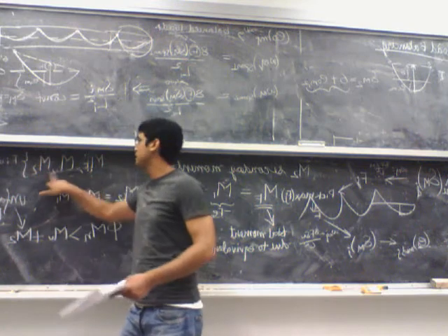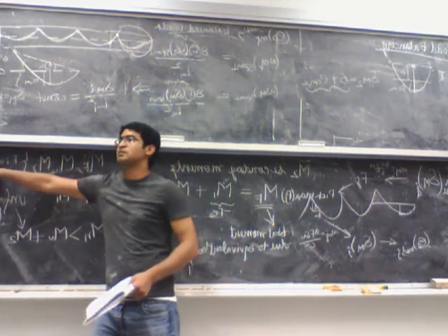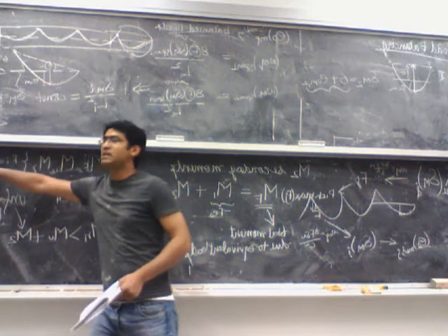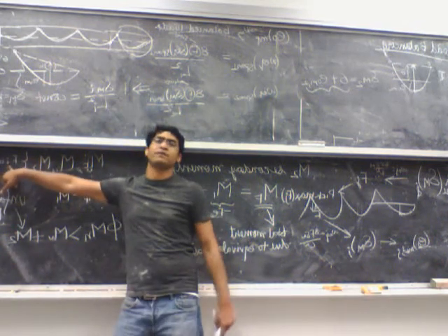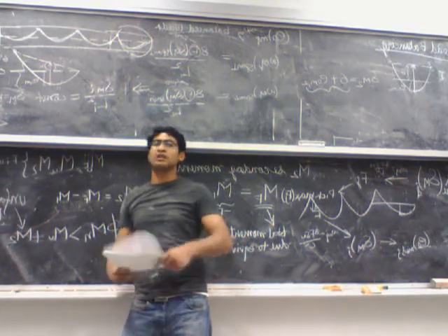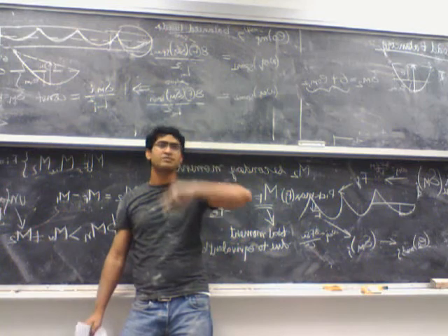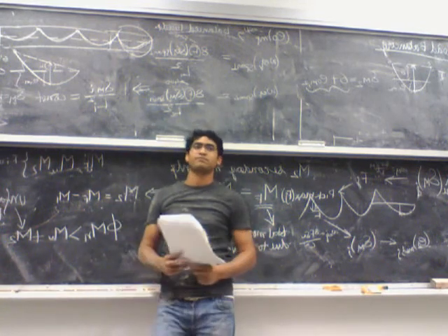You just multiply all these values by eta, and you get all these numbers for the effective pre-stressing force. If you calculate it based on F, divide by eta and you get all the numbers for Fi, because it's still a linear system. So if you increase the load by a factor of eta or decrease it by a factor of eta, your moments also scale by the same factor.